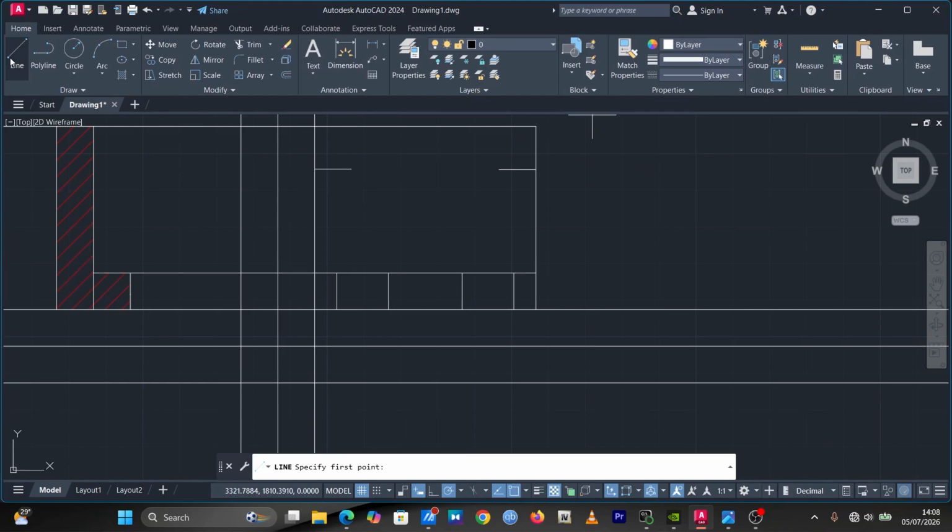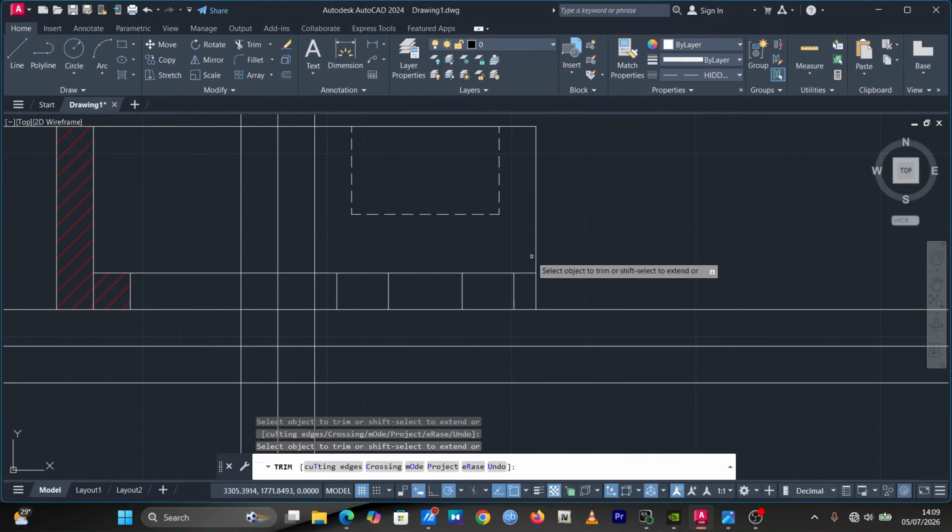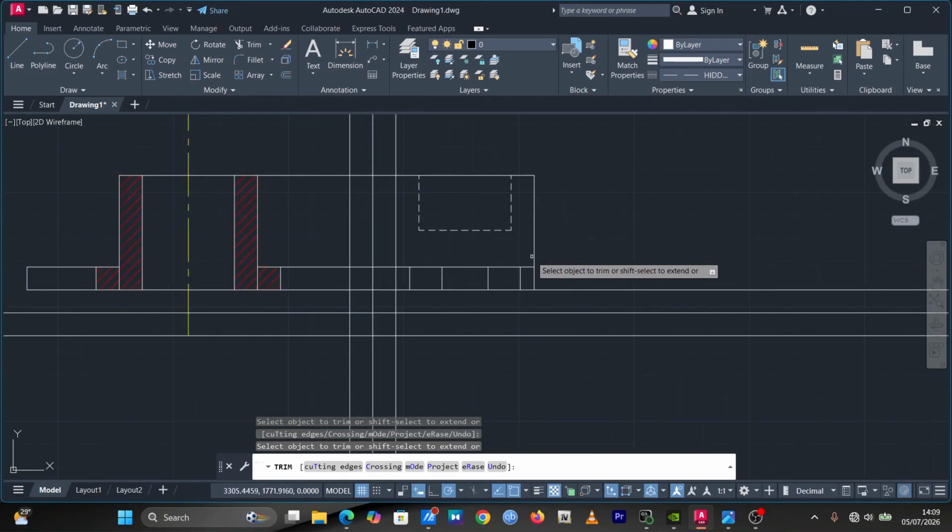And now you pick your line tool and then you pick your hidden tool because it's a hidden line. You draw your hidden line with a height of 24. So you cut and a distance of 40, because if you section 10 on the left and 10 on the right, the center is going to be left with 40. And then you just join it up here. When you are done, you trim these lines. You trim these lines also. So we are going to have something like this.